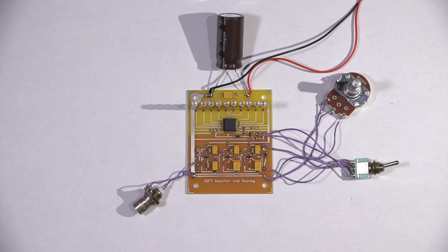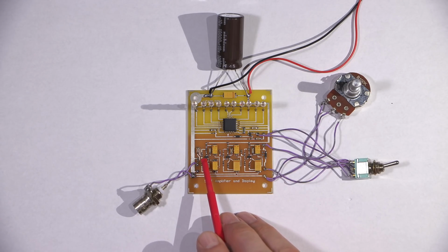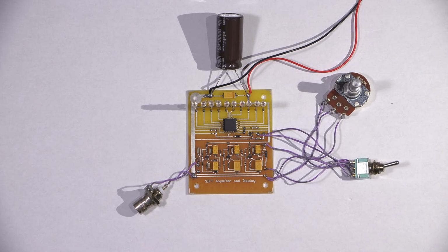Now, this can be used for any type of amplifier circuit, whether it's vacuum tube or solid state. You basically just need to know where to put the probes. There's a lot of things out there that will aid you in your troubleshooting procedure that has nothing to do with the schematic. A lot of the time, just knowing the pinout and what type of transistor you have on your circuit board is enough to get you going. Same thing with a vacuum tube. If you know what type of vacuum tubes are plugged into the circuit, you can very easily find out where the cathode, grid and plate are,